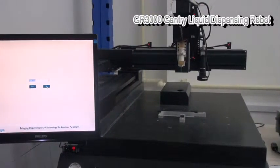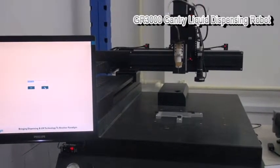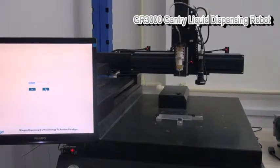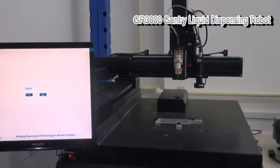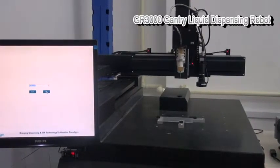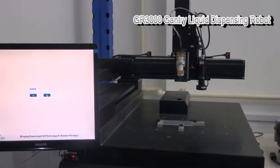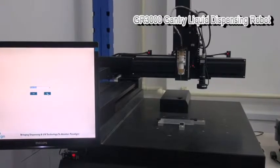So once you enter the position, every time the robot moves, it will go back to the same position. But when you change the needle, even though the robot goes to this position, the needle will be like that. So even if you go to the same position, when it dispenses, it may dispense here rather than here. So that process will make sure that if the needle is like that, when the robot dispenses, the robot will move this way such that it dispenses at the same position.